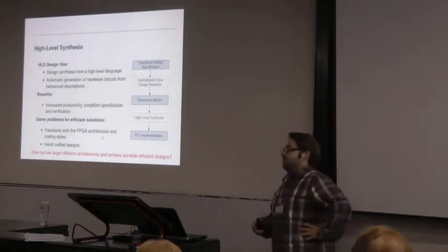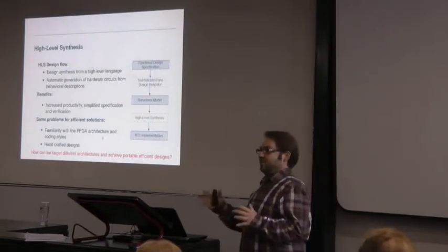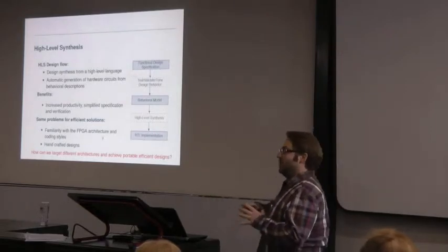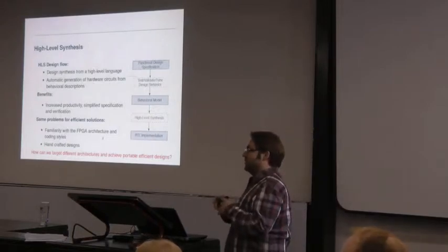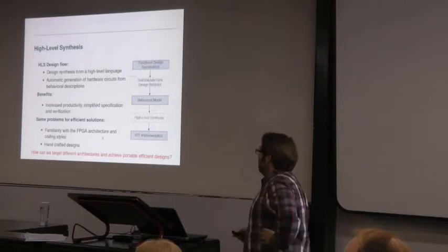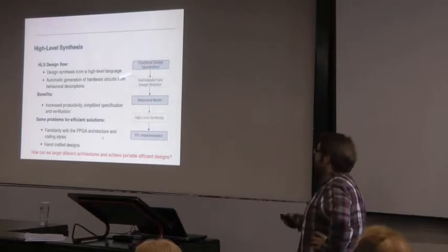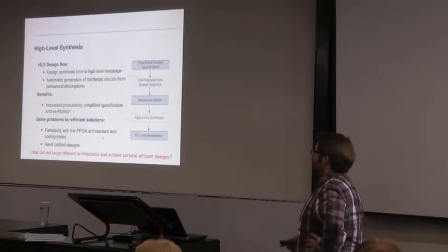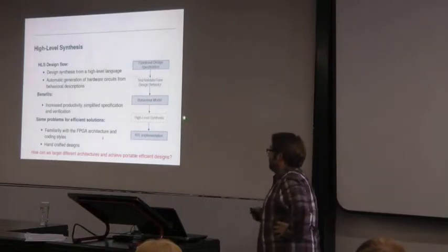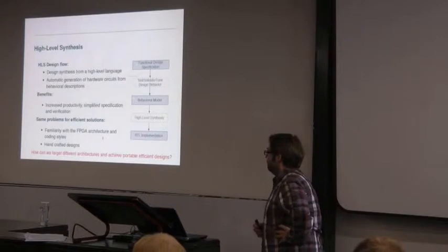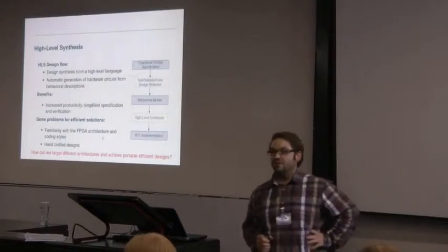You're lucky if you can accept a flow like Altera's, as introduced this morning, where you can download your whole FPGA system, and they make all the interconnects and all the I/O already for you. But most of the time you'll use high-level synthesis to simply make one accelerator in your system. So the benefits are increased productivity and simplified specification and verification.